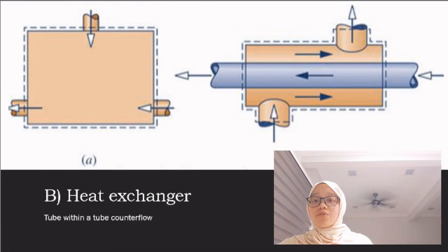One fluid will flow in the inner pipe, and the pipe will be enclosed with another pipe, where the space between the inner pipe and the outer pipe will be filled with another fluid, and thus the temperature difference between the two fluids within different pipes will cause the heat exchange to occur from the hot fluid to the cold fluid through the wall of the pipe.